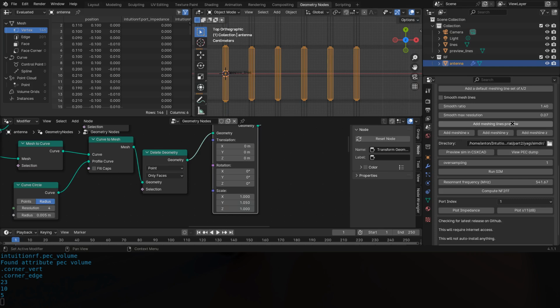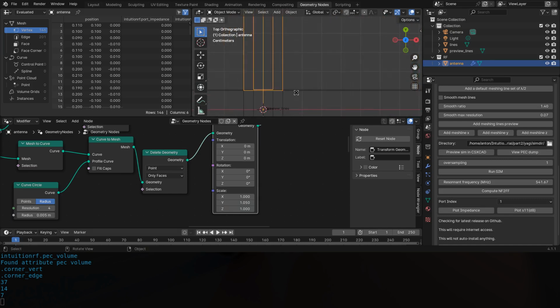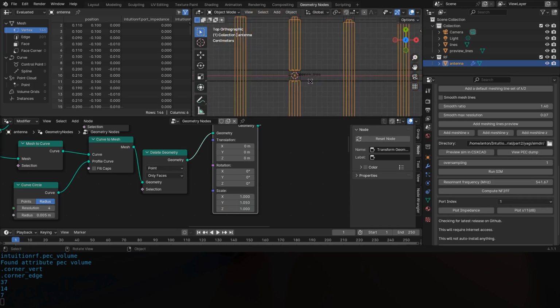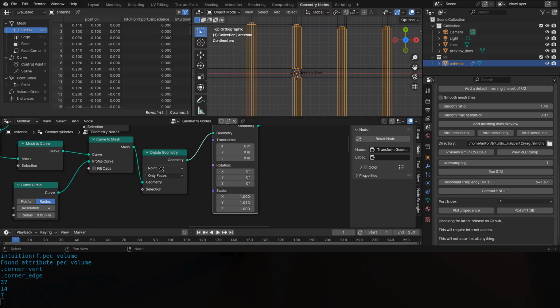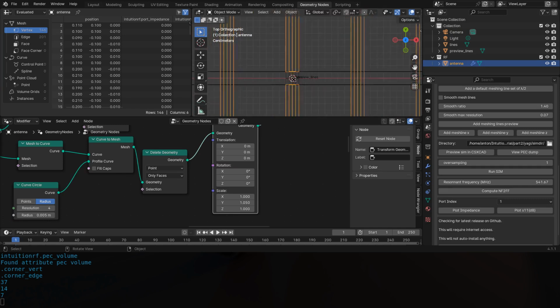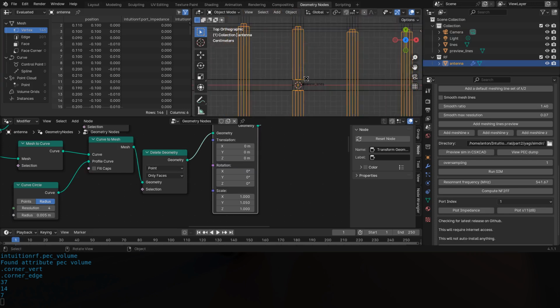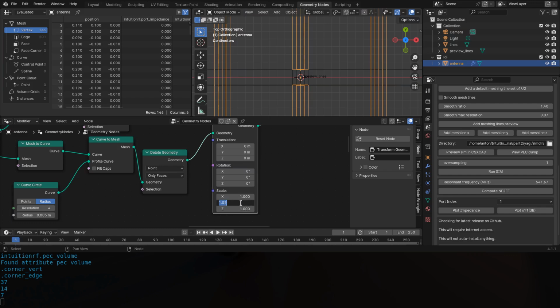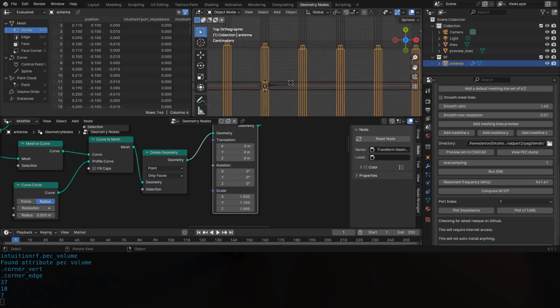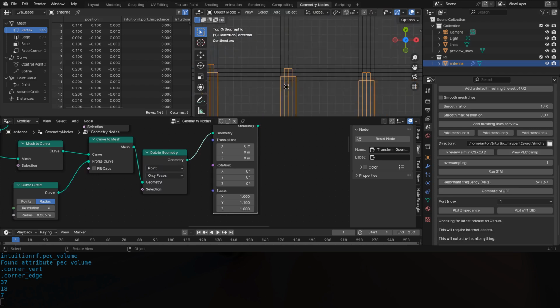Okay, and now if we show the meshing preview, as you can see, we've got some nice meshing lines that go all the way. Now those two are close, and that's expected. It's because we have this driven element port that scales around the origin of the object, so you get a 5% scaling on something that's not already very large to begin with, so it gets those two lines together quite close. So that's probably not what we want, so what we can do is make it 10% maybe. Okay, so that's still quite close and probably not what we want. And then we also get some meshing that's quite close here.